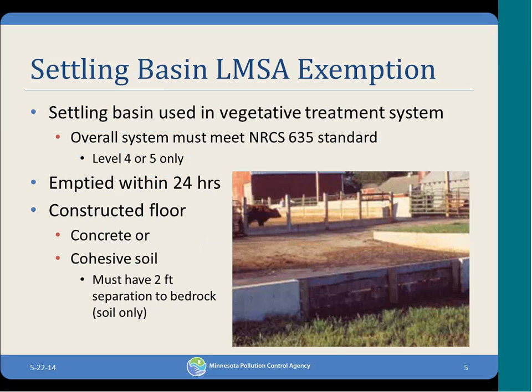The settling basin exemption for an LMSA is for a settling basin used in a vegetation treatment system, as an example. The overall system must meet the NRCS 635 standard, level 4 or 5, and if that's something you guys want clarification on, I can get that to you as well, or you can look it up. It must be emptied within 24 hours. The constructed floor must be concrete or a cohesive soil, like a basin would be required to meet. It must have 2 feet separation to bedrock if it's soil only.